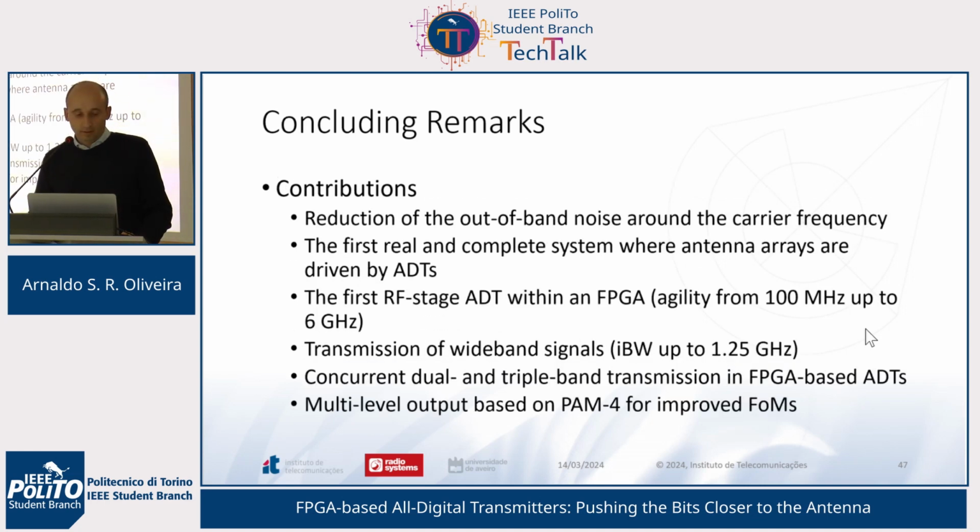These are a summary of our contributions. In the first contribution, we reduce considerably the out-of-band noise around the carrier frequency, allowing us to relax the filter requirements. We proposed the first real and complete system where an antenna array was driven by an all-digital transmitter.